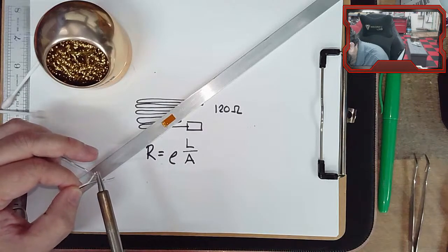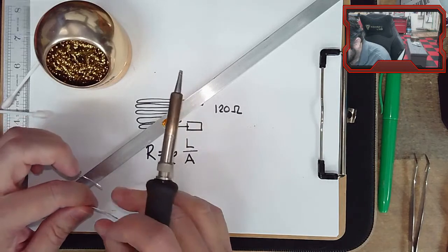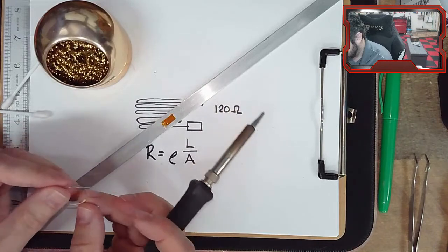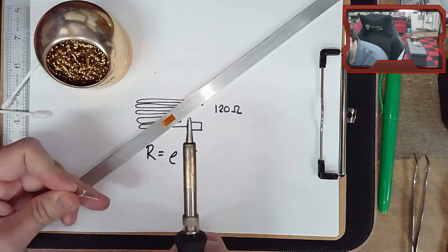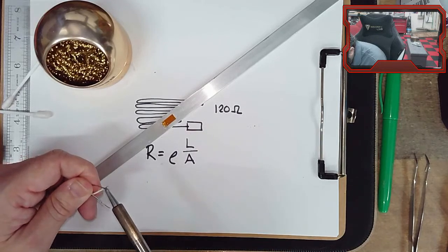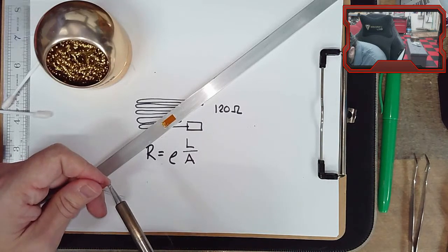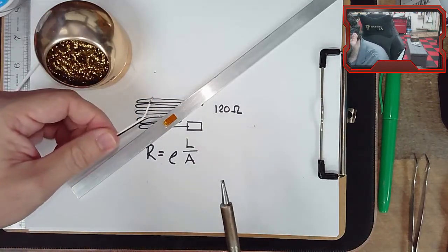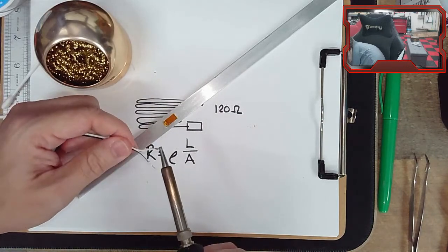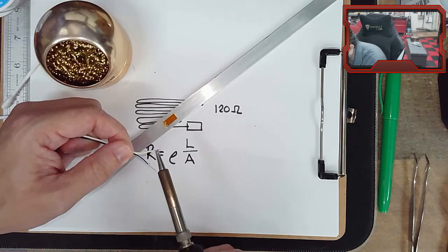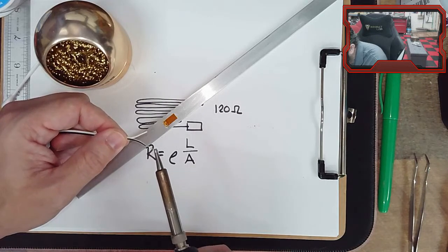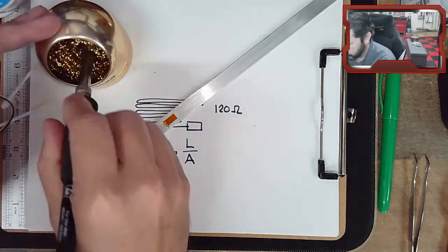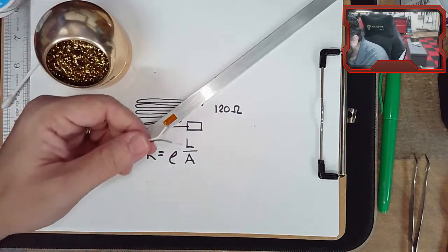So if we start out with solder already on our wires and our pads, then we don't have to worry quite as much about getting solder and wires and pads all in one place at one time. I'm just having trouble because I don't have any helping hands over here. All right, so now we have soldered on here. That one's a little blobby. I don't like that. Oh, I guess that's another thing that could go wrong. If you get too big of blobs, then you can actually connect them together, and that's going to be a problem.